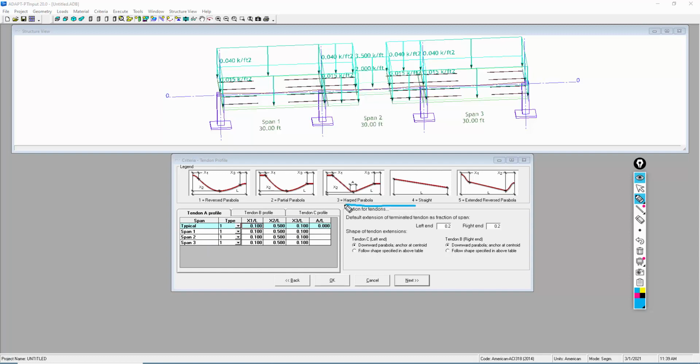The option for tendons here, this really relates to the add tendons. How do we anchor the add tendons? If they're, for example, 20% of the span length behind a support, how do those get anchored? Are they anchored at centroid? Is it a fraction of the span? So by default, it's 20%. You can modify that when we get into what's called the PT recycler window.